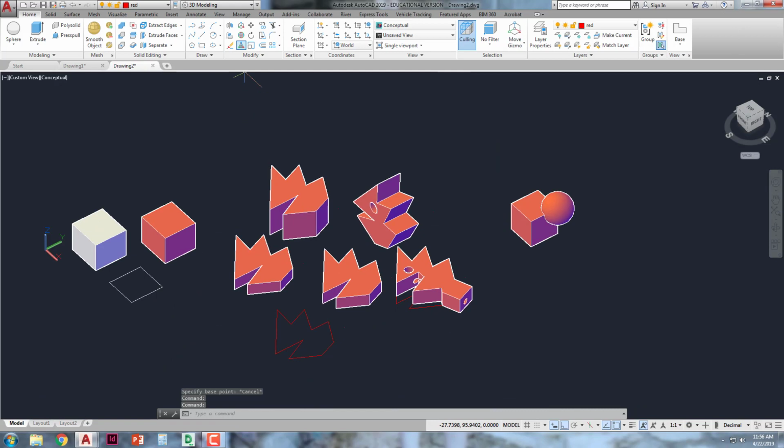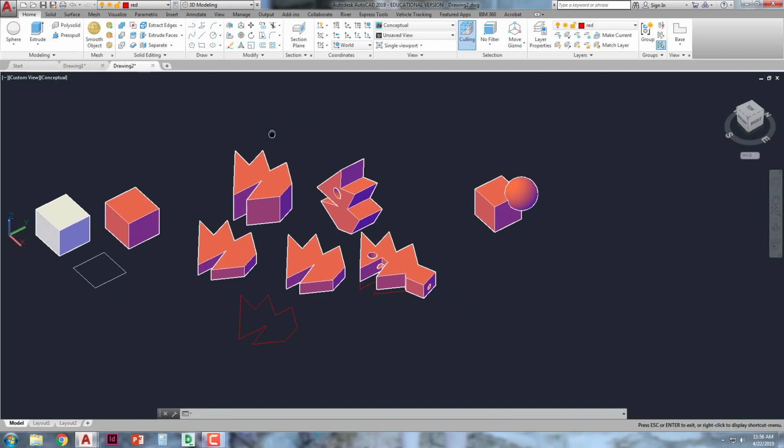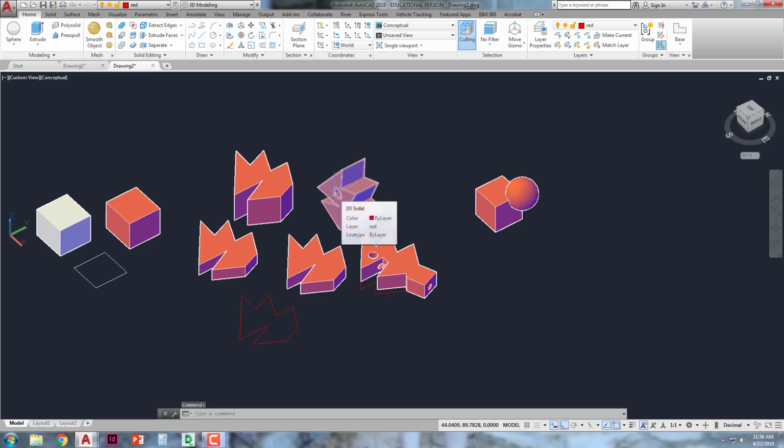There's also a 3D move command. So you remember when I was first drawing those lines and crazy stuff was happening along the Z axis and the X axis? That's the move command. When you're working in 3D, you can't always guarantee what's happening. It looks like you might be moving it flush across the plane in one direction, but you might actually be going back and down a little bit because you're in 3D world. So instead of the regular move command, you can do the 3D move command.